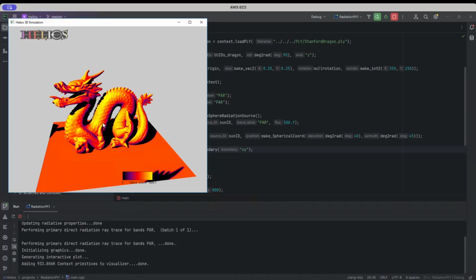It basically takes a bounding box around the whole domain and then uses that to create the periodic boundaries. So if you have some object hanging over, then you're going to get the bounding box that touches against that object. And then if that object is not the ground, you're going to get a gap in your ground.